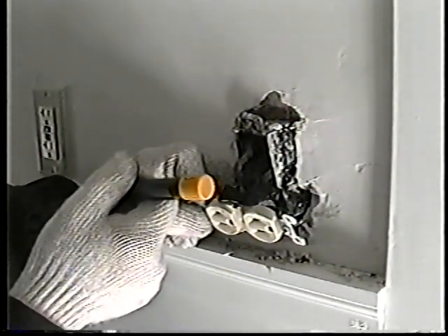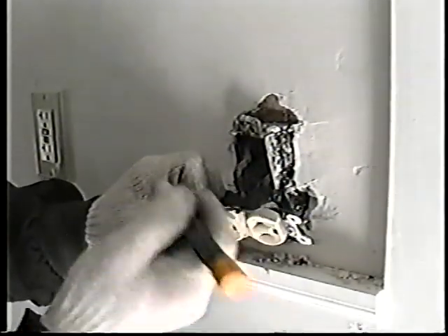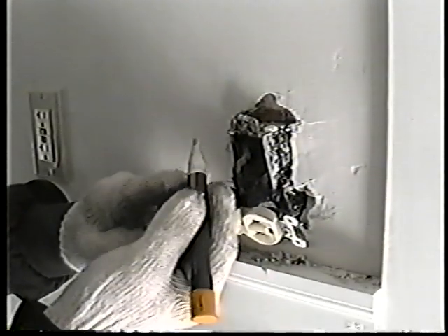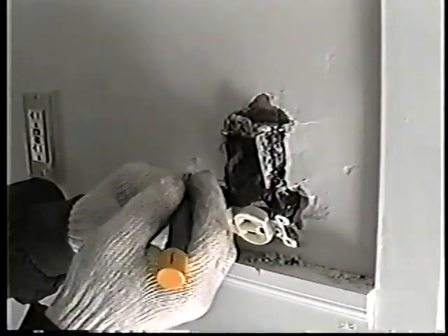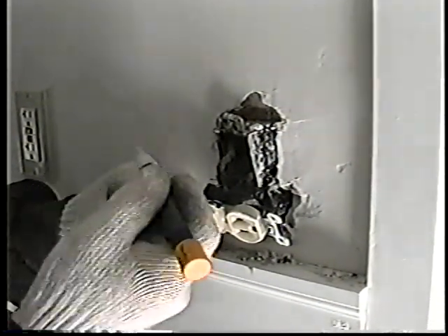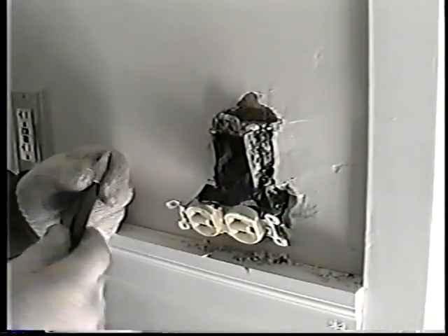One of the testers I was just mentioning is this one here, made by Amprobe. This will tell me which wire is actually the hot wire from the electrical panel. This outlet has no power, so you're not going to see it light up, but the white tip here will actually light red when I touch it near the wire that it senses power on. It'll only light on the black wire, and it won't light on the neutral wire, which is the white wire. That's one good way that we can test to see which one it is. It's not 100% accurate, so you can't put your life on it. It's a good thing to test it with a couple different testers that we use.